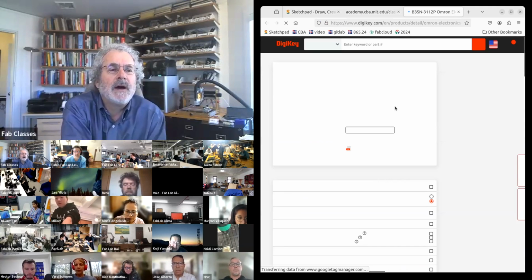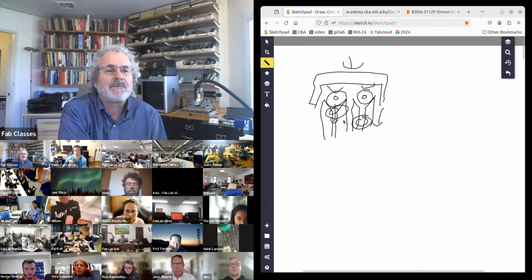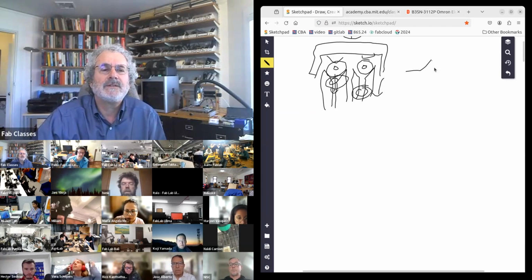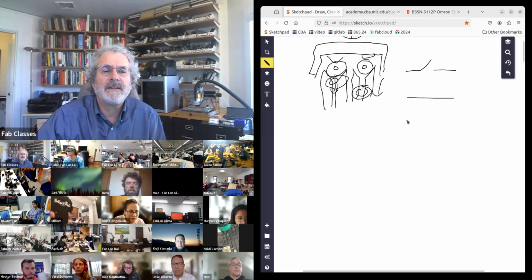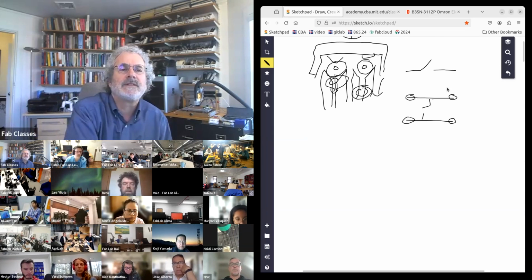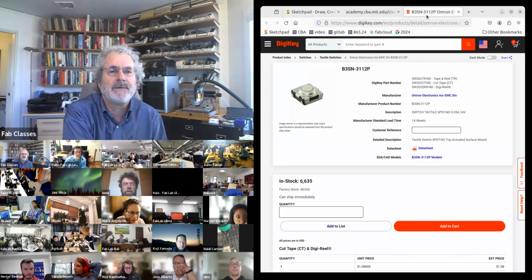You've already seen buttons. This is a classic button. The button electrically is normally open, and when you push it, it closes. Internally, if you look on the back of it, there's a line, and there are 4 pads, connected in pairs, so you can connect to either one. The switch that's normally open is a push button, and it closes when you push it. So that's a button.